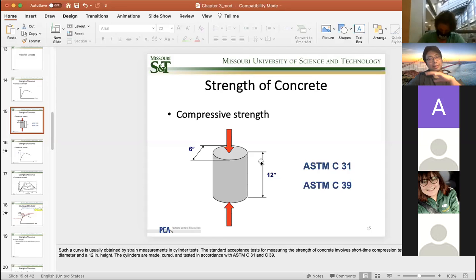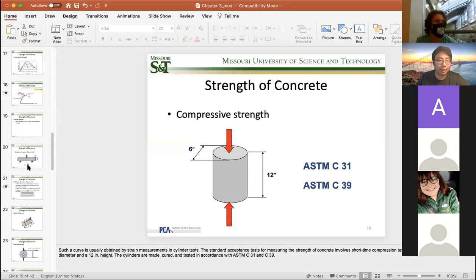In the construction industry, if you cannot achieve the specified 7-day strength, you need to knock your building down. So it is very critical. Then we use the 28 days results as the compressive strength of the concrete. So be very careful here.